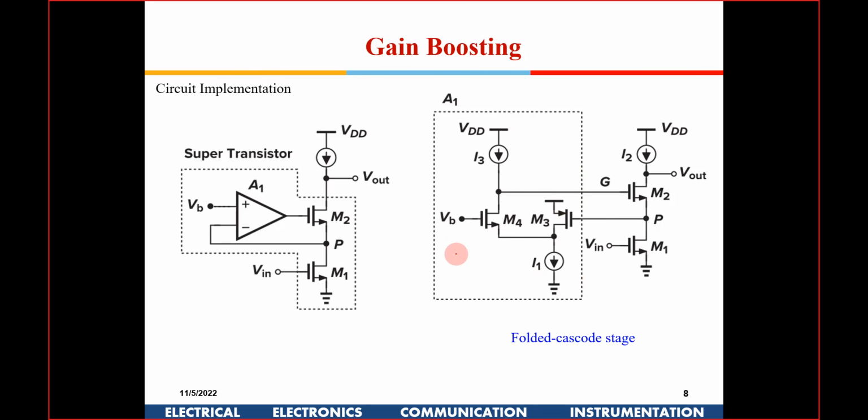This is a folded cascode. Again, if you don't want this particular capacitance also to get affected, you could have a cascode structure out here also. This is coming here to the gate. You remember this, right? You did your assignment also. This is a folded cascode.